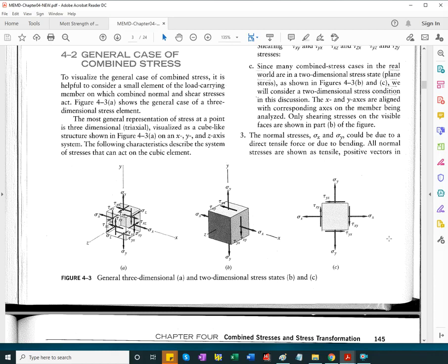If that pipe is submerged deep in water, like thousands of feet at the bottom of the ocean, there will be a normal stress perpendicular to the outer skin. An element to the inside of the pipe, and the pipe, again, is pressurized, is also going to experience a normal stress. Both cases, deep submerged or to the inside of the pipe, those are normal stresses, and compressive stresses normal to the element.